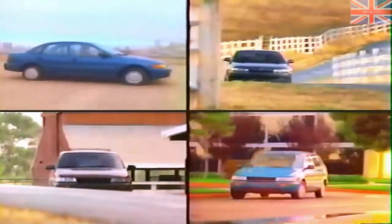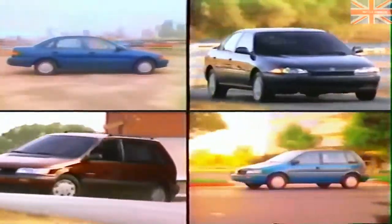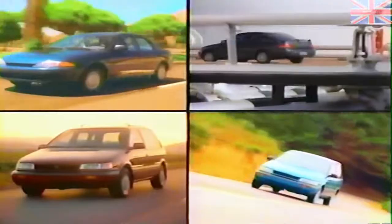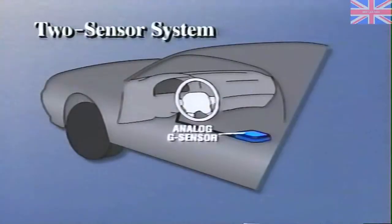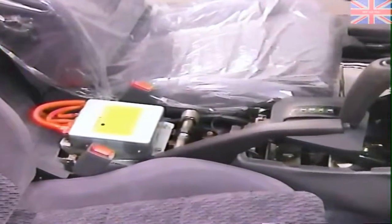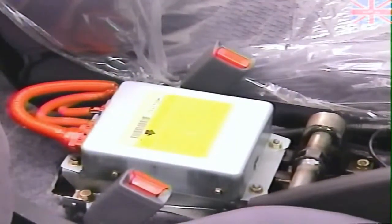The second type is a 2-sensor impact detection system used in the 1994 Colt, Summit, Summit Wagon, and Colt Vista. It uses an analog G sensor and safing G sensor, both located inside the SRS Diagnostic unit. These vehicles use only a driver's side airbag. The SRS Diagnostic unit is located under the rear of the center console on all of these vehicles.